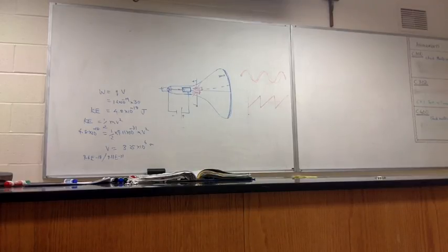Now, this is something that is dangerous to play with, because, as I said, the voltage is what? 20,000 volts on the picture tube. Between the picture tube and inside here is 20,000 volts. And of course, the circuits will have that. So if someone is not aware of those things, they will end up touching and getting a fatal shock.